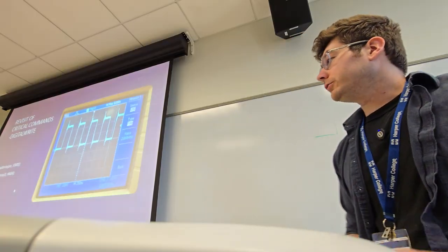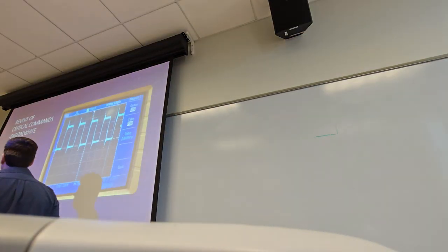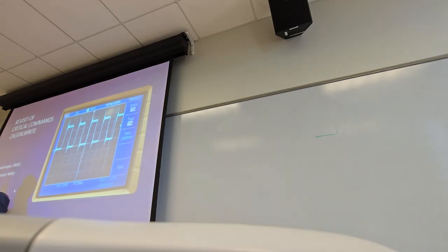All right, here we're talking about digitalWrite. digitalWrite also takes two arguments. Just like before, we have the pin argument. Again, it can be 0, 1, 2, 3, 4, 5, whatever, including A0 through A5. And then the state can be high or low.